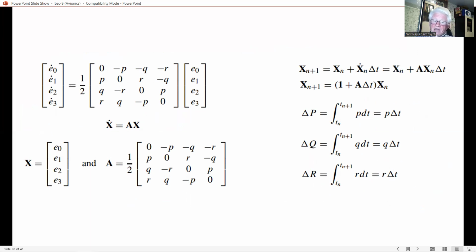First, they apply to all attitudes. Second, the error equations are bounded by the constraint equation. And third, the numerical value of each parameter always lies in the range from -1 to +1, so easing the scaling problems in the computing mechanization.